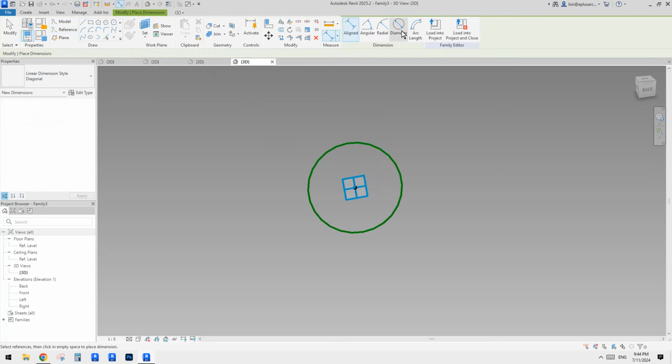And now we can just select the profile. So here, yeah. Profile, control select, and control select the path and create a form. Okay, so then select this point, or you can just drag this to this end. This one, there's no work plan, so that's fine. Select the point and type 1, so it will go to the other side.